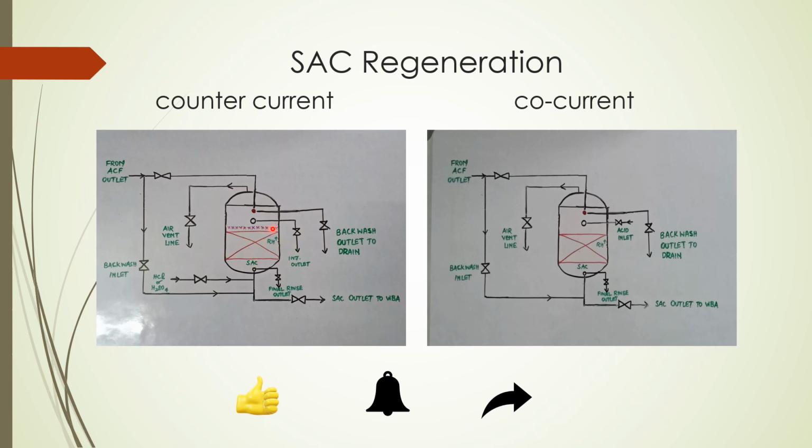So this inert resin will play a vital role during the regeneration. When the regeneration is given from the bottom, we have to keep downflow water or air. Normally water is preferred, so water is first set as downflow to be taken from the regenerant outlet header. This is the drain. Water downflow is maintained. That will keep the inert contact ball or inert resin intact. It will compress the resin volume, resin bed.